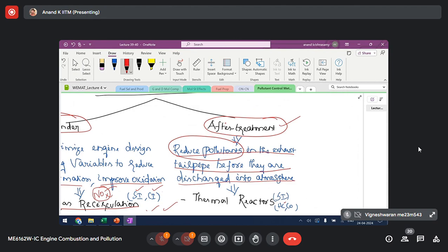So you are talking about a dual fuel engine? Exactly, yes, sir. In a dual fuel engine, you can use any high octane fuel as a port injected fuel. Mostly gaseous fuels are used as a port injected fuel, like CNG, hydrogen or biogas. They are injected in the port. But the problem with these fuels is they cannot ignite by themselves. The cetane number is very, very low. So you are injecting diesel directly into the engine cylinder to ignite this pre-mixed fuel-air mixture. And any of the high octane fuels can be used in the dual fuel mode, because anyway you have diesel as an ignition source.